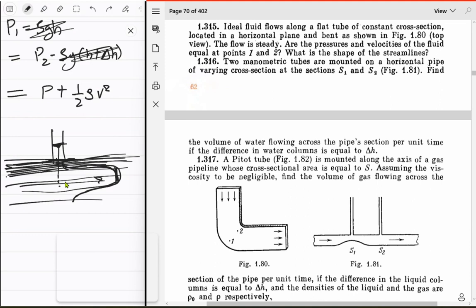Okay, there's viscous forces, just the changing velocity involved. What about the pressures though? You see these blocks, they only have forces along the x direction. They don't have forces along the y direction, right? So this volume element won't go in this direction. It will just continue moving forward. What that means is that there's no gradient of pressure in the y. Yeah, okay, right. That makes a lot of sense.